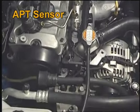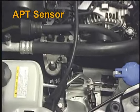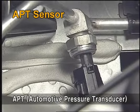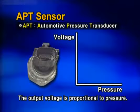The APT sensor for detecting the refrigerant pressure is installed at the high pipe line connecting the condenser and evaporator. It is made of semiconductor piezoelectric element. It has the proportional characteristic in which the output voltage is increased as the refrigerant pressure is increased.